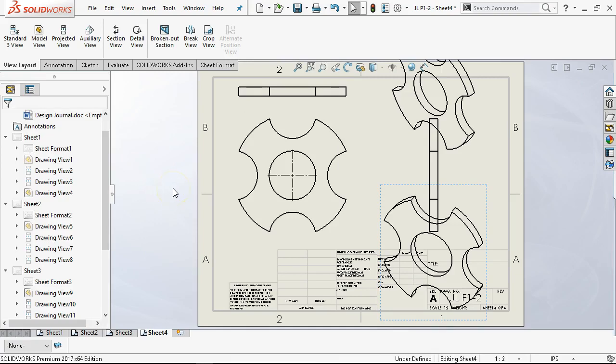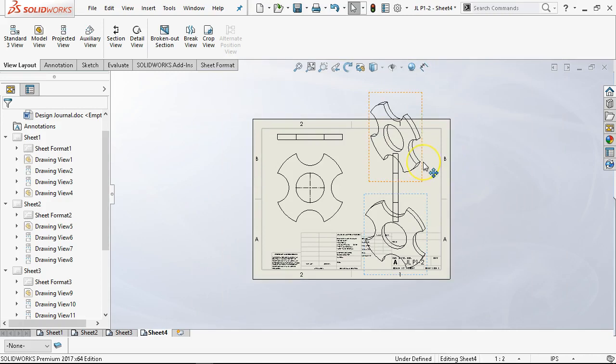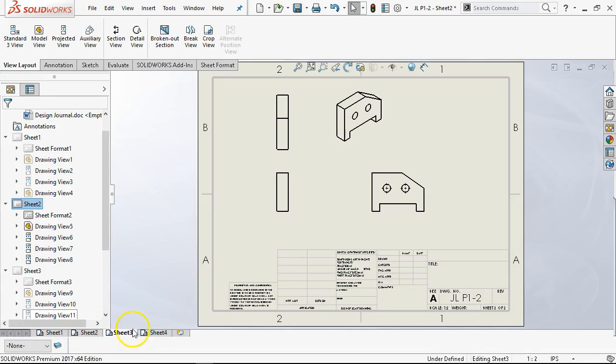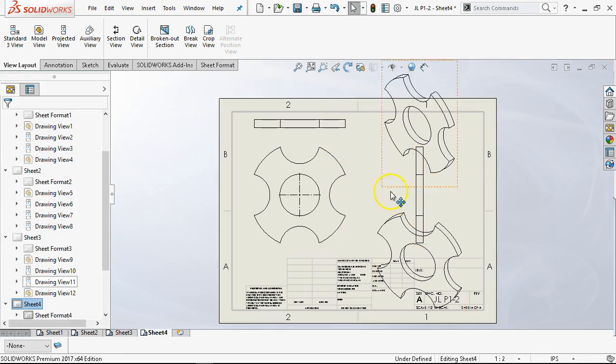All right, scaling. Well, we haven't done any scaling. I'm going to say my strategy, my practice, and we won't go through all 18, but you can kind of see that once I got on a roll here, I could go ahead and place all 18 sheets in a matter of minutes. Then, after I've got everything in the order that I want it, and start that sequence, then I'll go back through and set the scales. Then I'll start doing the dimensioning. So it's kind of get everything set up, get everything visible, viewable, and go back through each of the steps. All right, so that was the only one that really didn't scale very well.